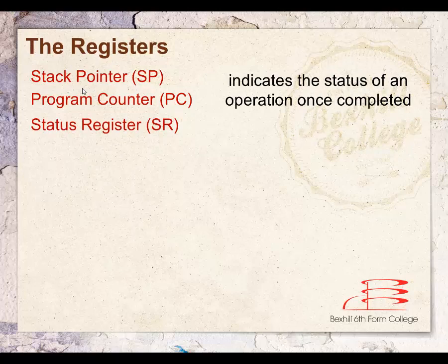The status register. There's a whole series of status flags in the system. When you set a value, they're called flags because the idea is to mentally imagine that they pop up. They don't. They're set as 0 initially, and if something happens, they're set to 1. One such flag is what we call an add with carry. If I add a number up and it exceeds the number of bits I've got available, then the carry flag will come up to tell me that the number is bigger than I've actually got. There are a number of flags inside of the system.